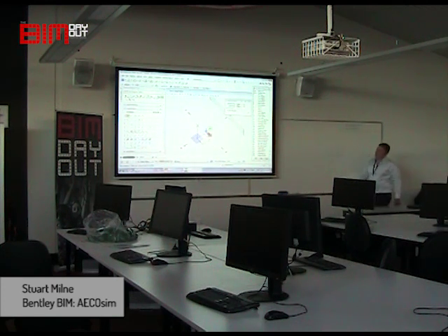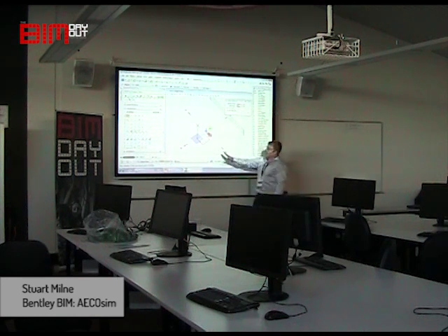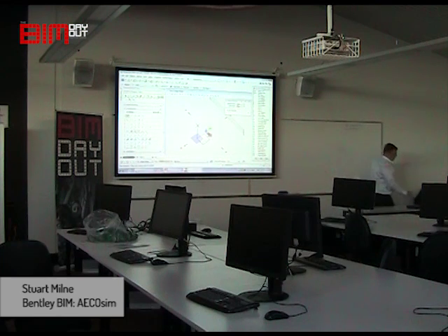Now, at the moment, our AccuDraw compass is lying flat on the floor. So that means any line I place in any direction will be lying flat on the floor. So what we need to do is rotate our AccuDraw compass so we have a z-axis. You've got two options here. You've got F for front or S for side.